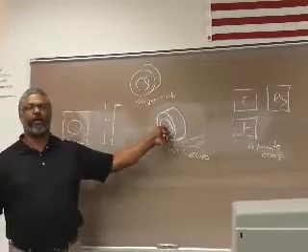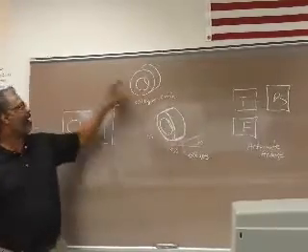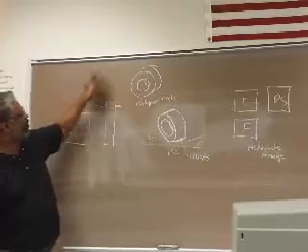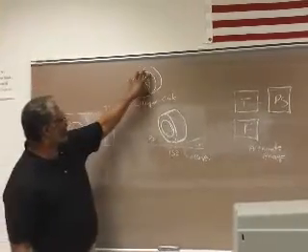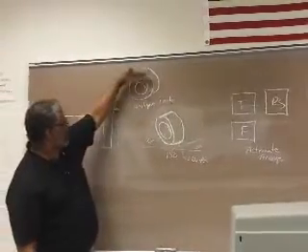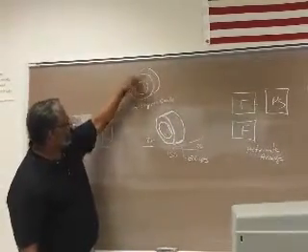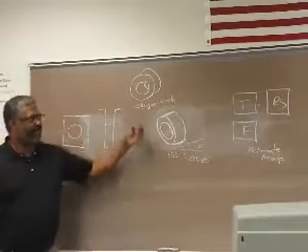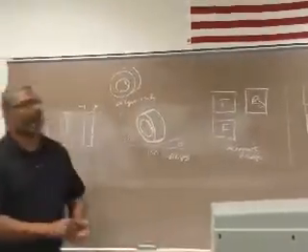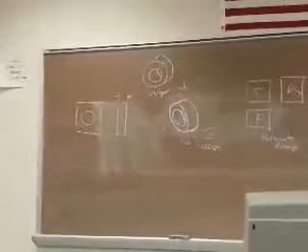I just have to redraw this as an ISO. Here I could copy this here and then copy this back at an angle equal to that thickness, trim out my lines that I should trim out, and I got it done. So that's one of the reasons for dealing with obliques.